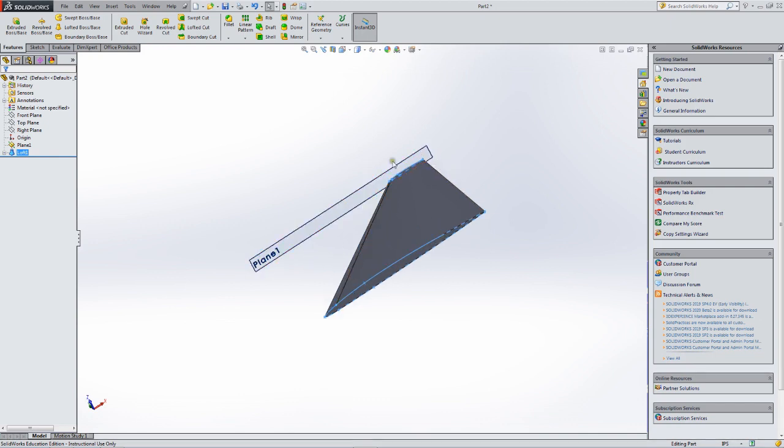That move function normally is an XY thing, so let's do that first, I guess. And the way we have to do that to edit those sketches is we have to expand out the loft. The sketches have been consumed, so what that means is if I click over here, the sketches are not visible anymore. You can make them visible.